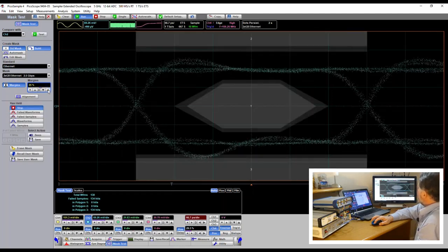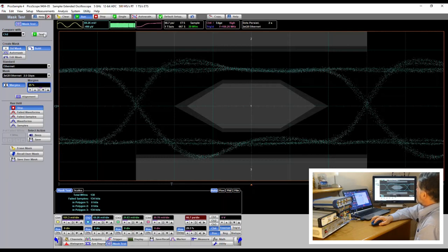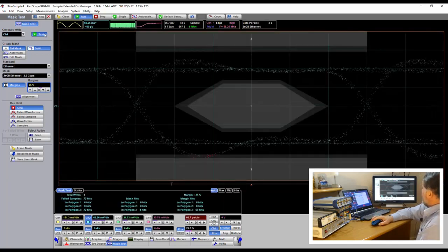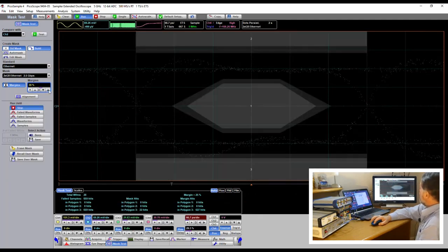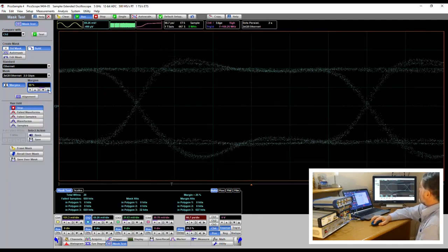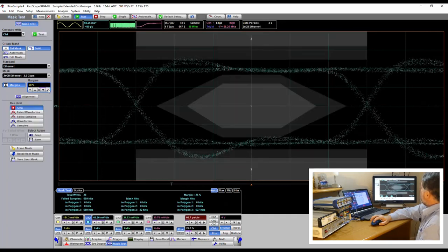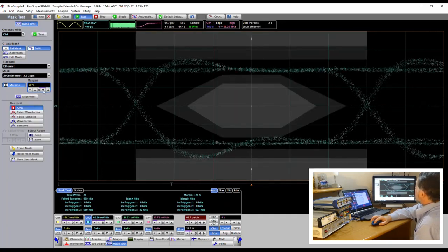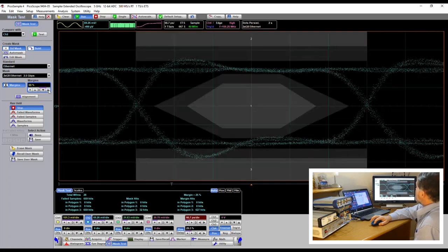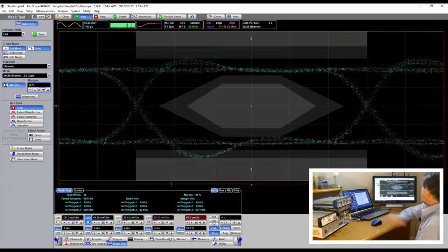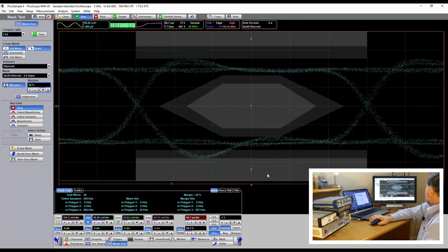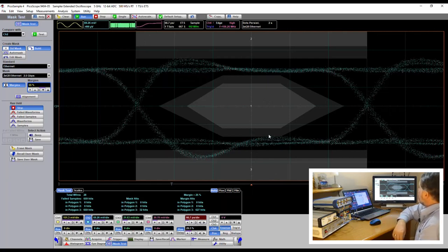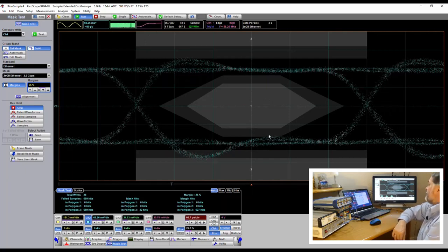Here we go, and of course if I re-establish the test, we are now heavily failing against polygon 3, and we can see what margin we've got against the other masks. You can see I'm just beginning at 60% margin, I'm just beginning to hit the other polygons there. So I've got an infringement on 2 and an infringement on 1 here, with a 55% margin added.